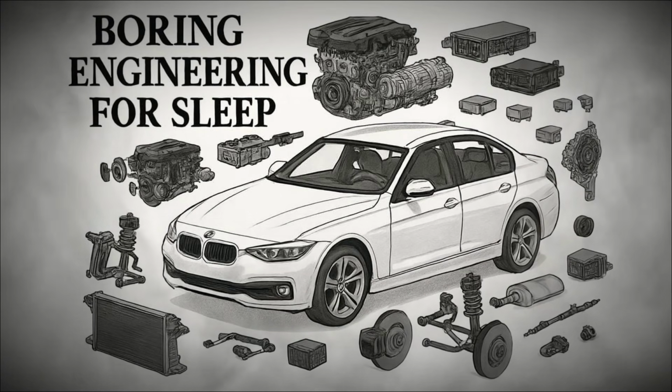Yet the traditional 12-volt system, with its battery, alternator, and starter motor, remains the foundation upon which all other systems rely. Maintenance of the electrical system is vital, since a weak battery, faulty alternator, or worn starter motor can leave a car unable to start or operate properly. Regular checks of battery charge, belt condition, and electrical connections ensure reliability.